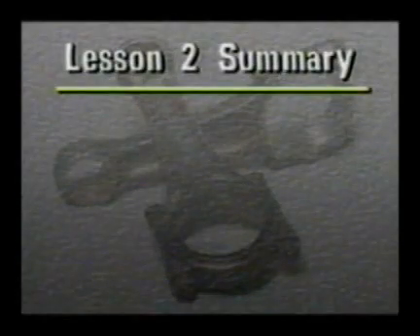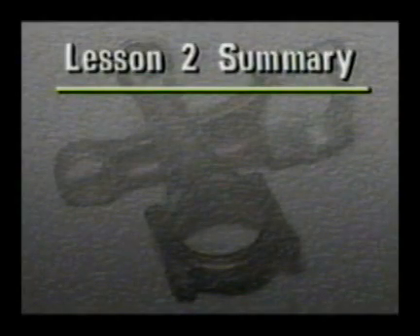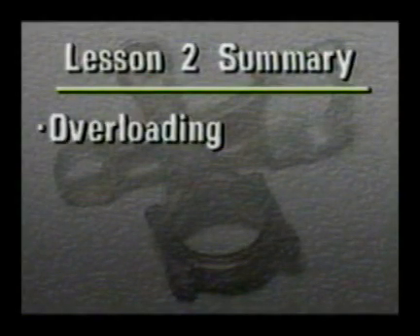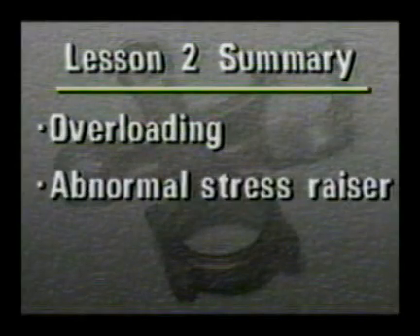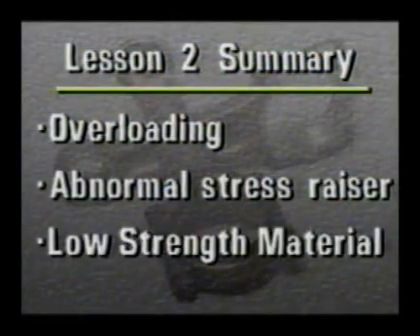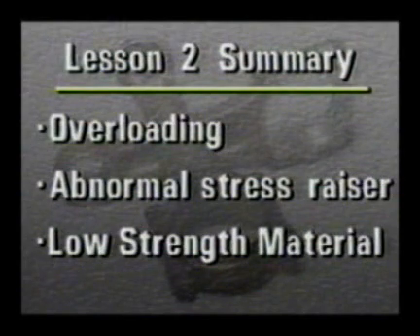During this lesson, you have learned 3 conditions that can cause parts to fracture. You learned that overloads can be applied once, causing ductile or brittle fractures, or they can be applied cyclically, causing fatigue fractures. You also learned that abnormal stress raisers or low-strength material can produce fractures under normal loading conditions.